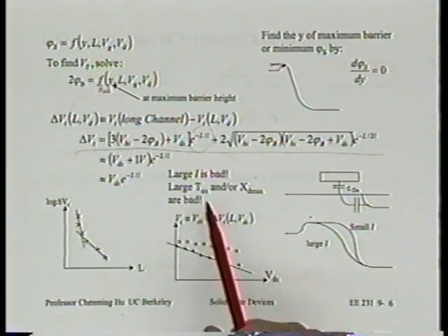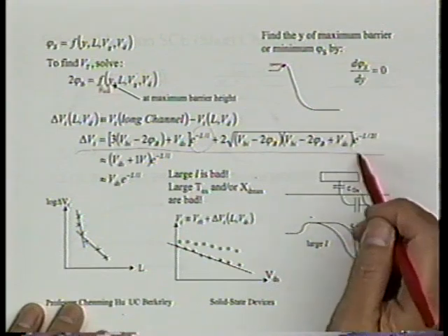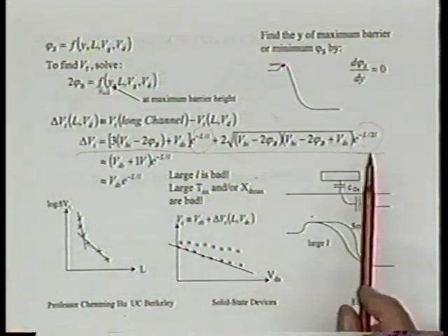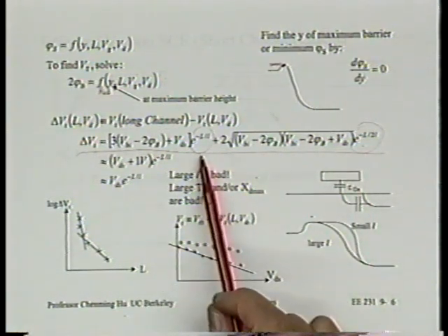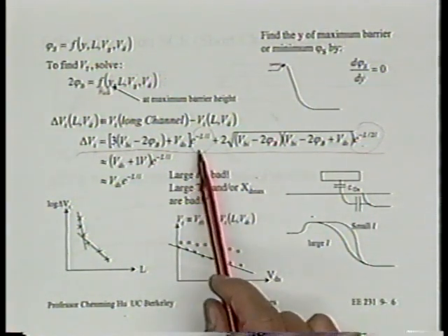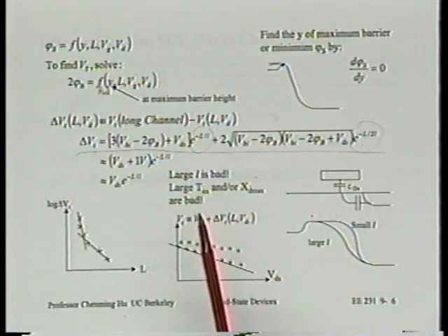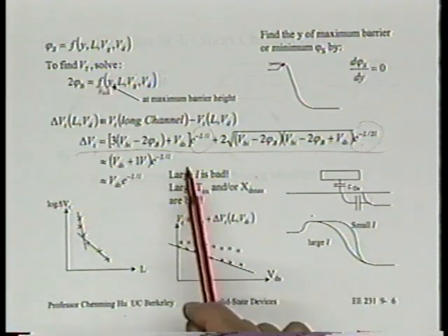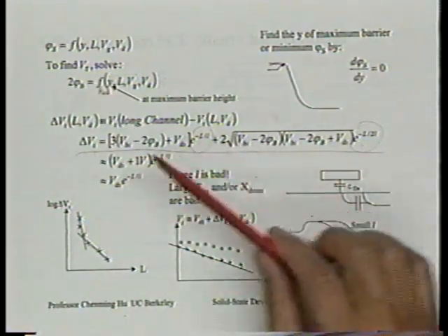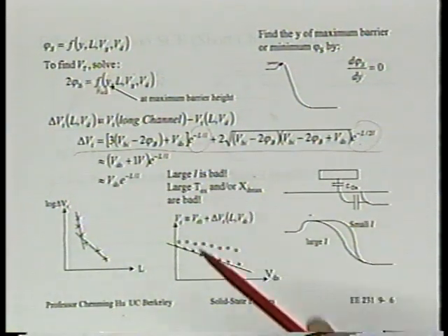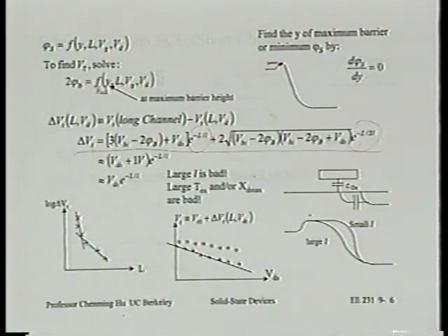But when we do that, we notice we need to take at least two of the Taylor expansion terms, not Taylor expansion now, expansion of hyperbolic function. Because we can expand the hyperbolic function into exponential functions. I mention this because it's really funny. So we propose that the delta Vt is an exponential function of L, channel length. And I think most people accept that, and it's a very good concept. I want you to remember that.